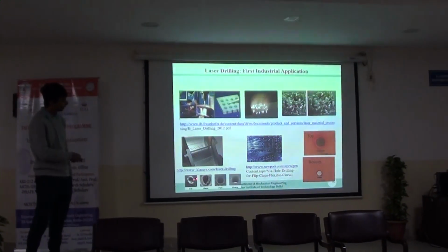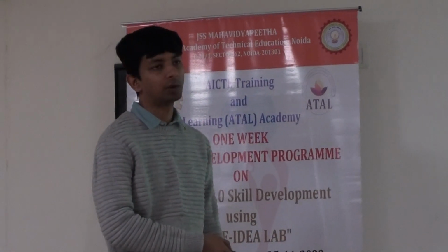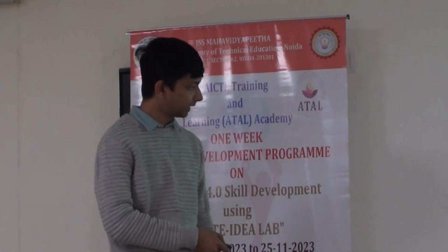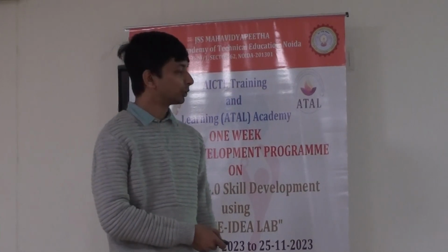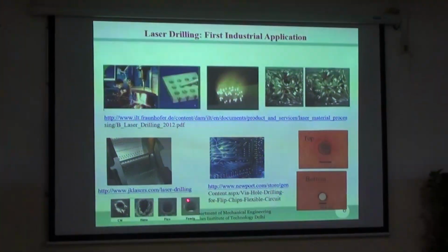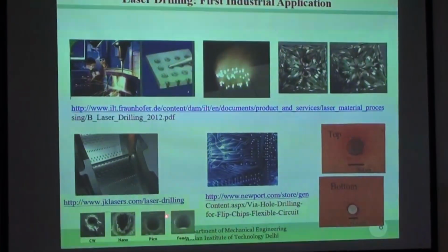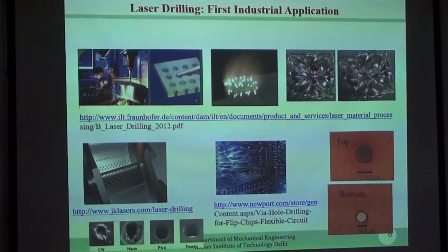Fine, if you see this particular figure, it shows that if I switch on the laser in continuous wave mode, see the cut quality. This is basically drilling, not cutting. And if you operate the laser in pulse mode, you get very good quality. So the idea is not that you have a laser and you just switch it on. You should understand the material processing regime, or the time domain that you want to work in, and select the laser power and the pulse duration accordingly. So it's not always good to have very high power lasers. You should understand the application, and then the time domain you want to work in. That is very important.